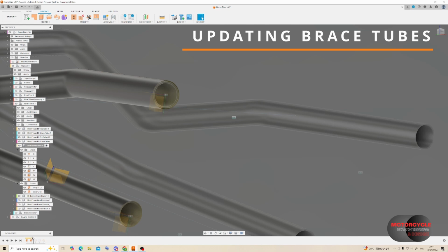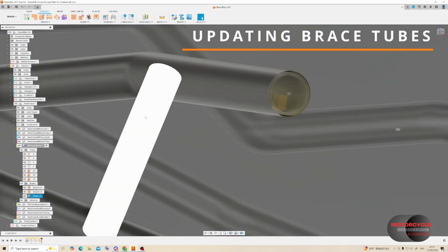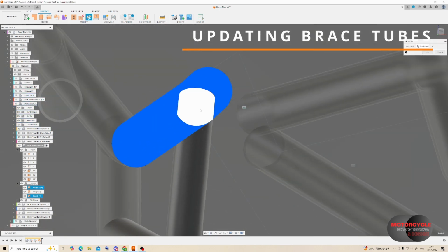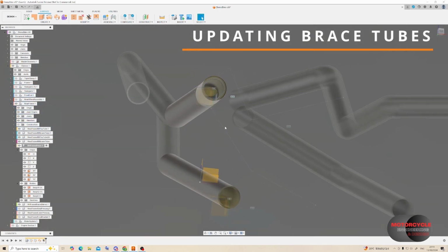So here we copy in the surfaces from the lower and upper tubes, and then we convert those to DM feature. And just a note, when you do want to convert any features, any surfaces to a DM feature, it's best to move those features to the beginning of the timeline because everything before it will also be converted to the DM feature.